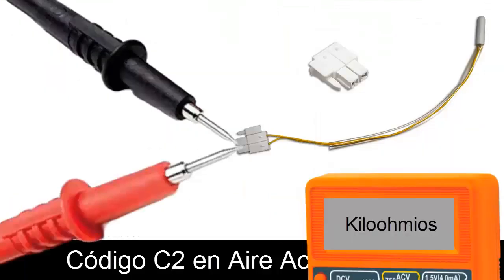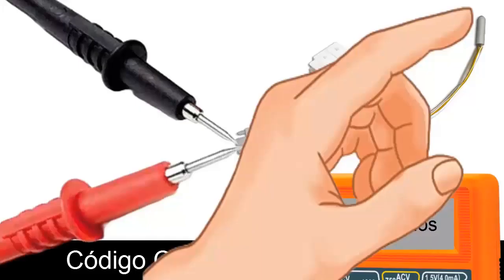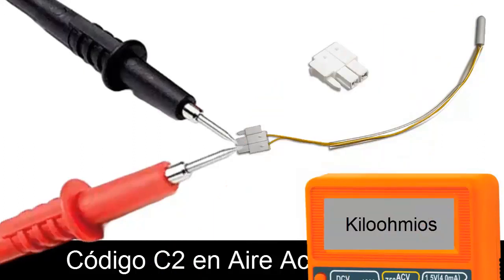D. Measure the thermistor's resistance. Turn off the unit, disconnect the sensor, and using the multimeter's kilo-ohm scale, measure the resistance value. If you have the sensor's resistance and temperature table, compare the values. When you rub the sensor with your hand, the measured value should decrease. The multimeter reading should never show 0 or infinity.